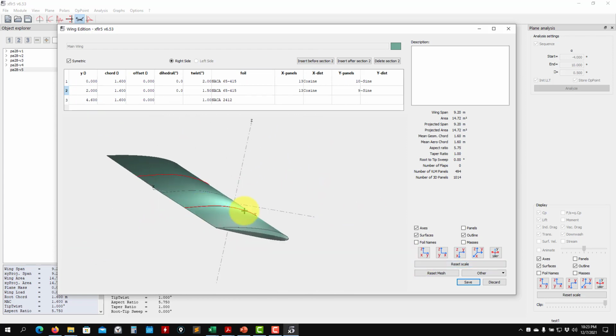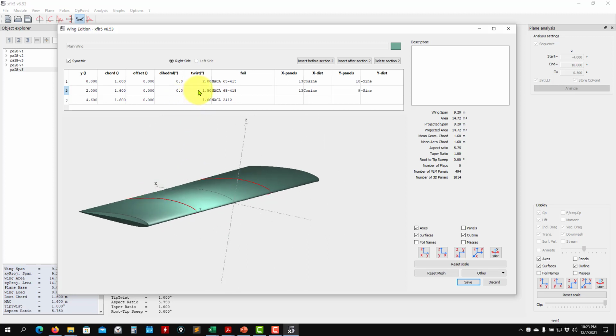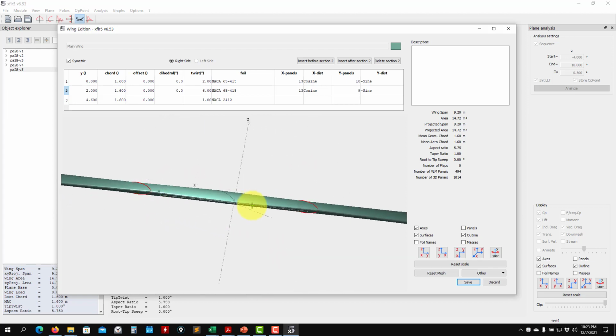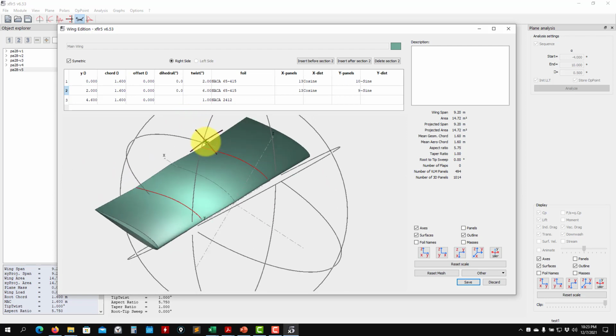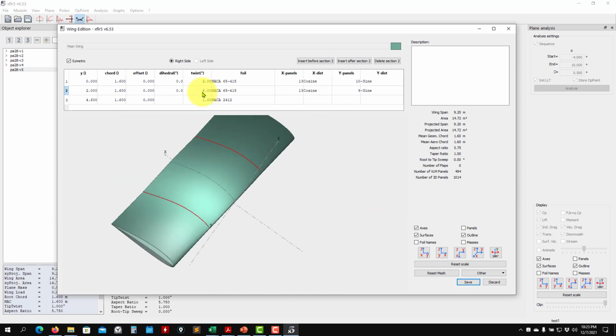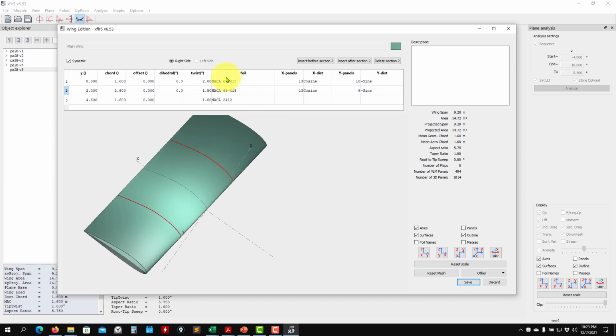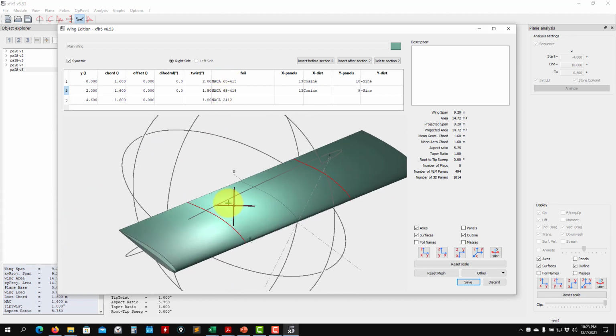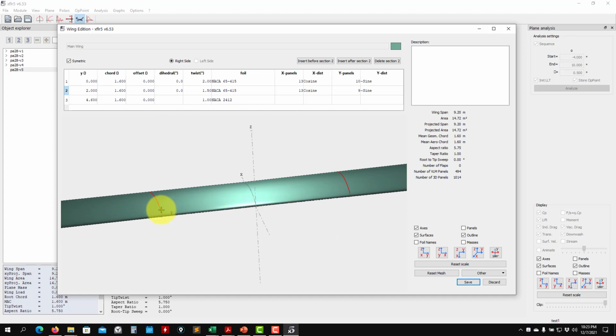And see that now that you have that section, you can control twist. So for instance, look at that, if I put 6, you're doing that, okay? So here you go from 2 to 6. So probably it's not very nice. Okay, so let's put 1.5 and I will leave this profile there. So see that I'm using this series 6 in all this section here, and then in the outer section you are doing the aerodynamic twist plus that geometrical twist.